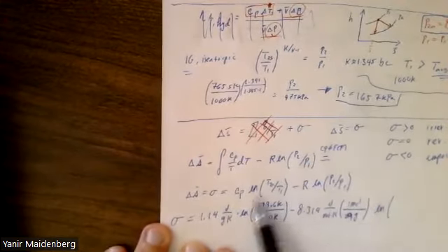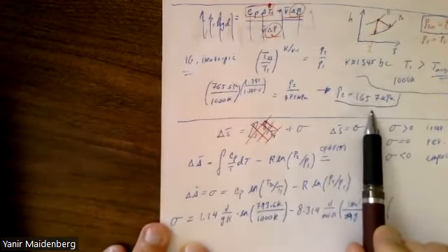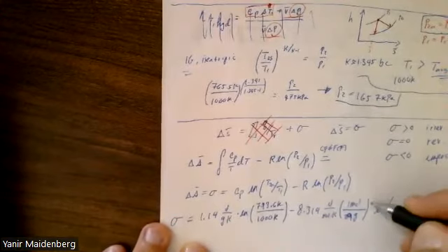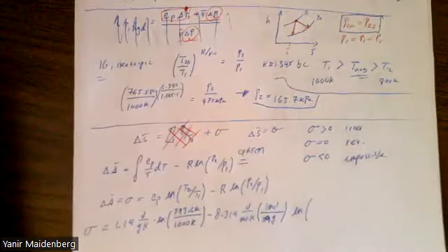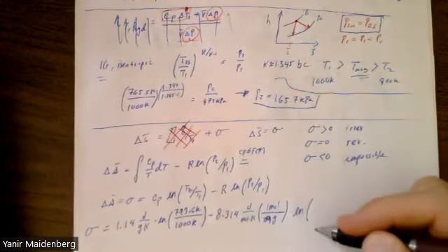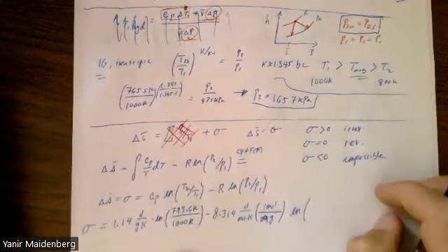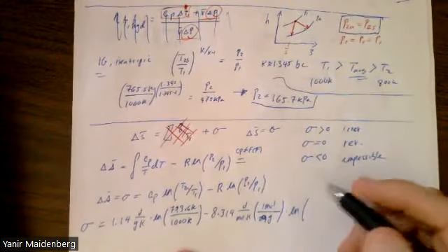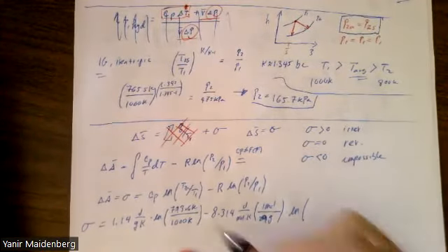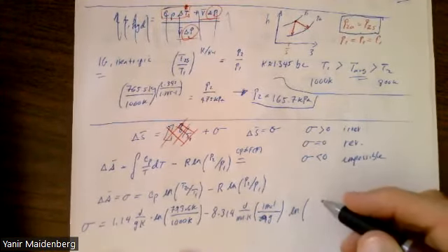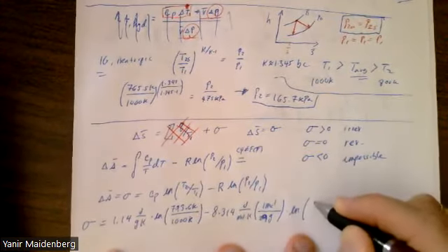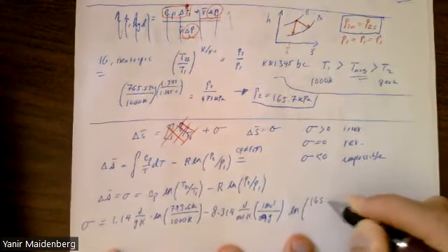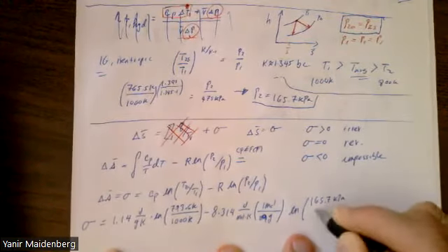P2 we just evaluated right up here is 165.7. P1 is given in the question as 475. It does not matter what units you use. You could use anything in the world because it's the ratio. You could use some made-up unit system because they're taking the ratio. As long as it's an absolute pressure, who cares? Same here. As long as it's an absolute temperature, it could be Rankine, could be Kelvin, whatever you want. Celsius won't work. Fahrenheit won't work. Degrees Newton wouldn't work. Just use Kelvin or Rankine. And here use absolute pressure, not gauge pressure, which we rarely use in our questions anyway.